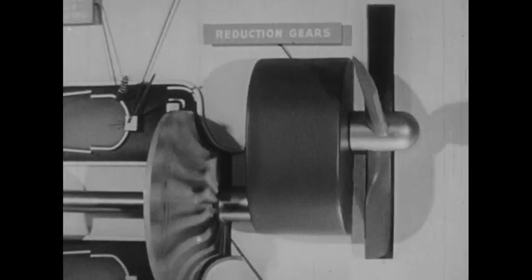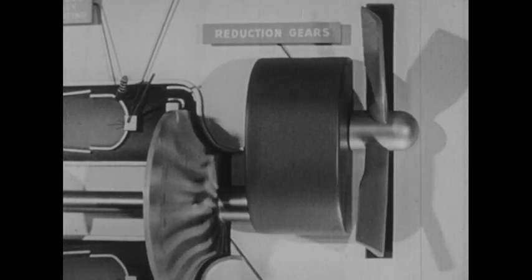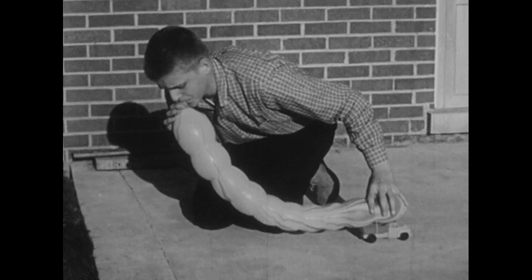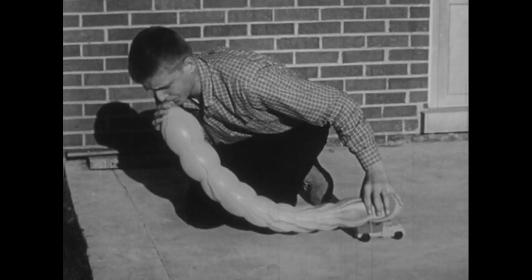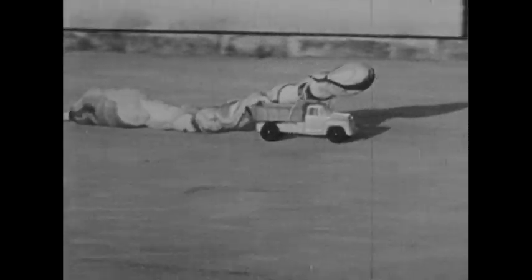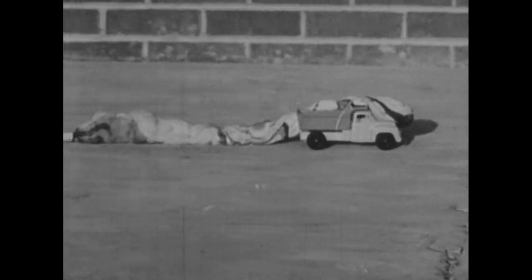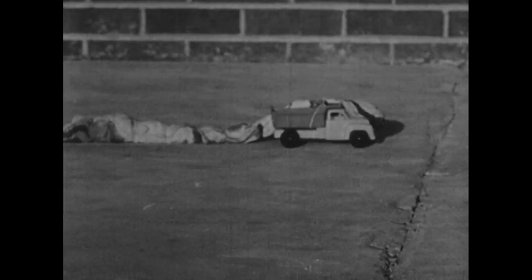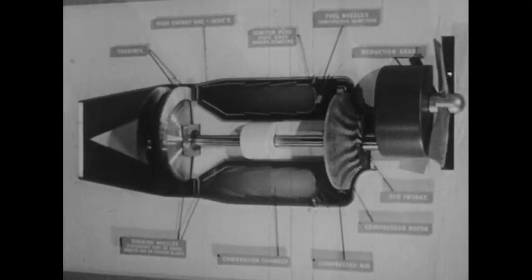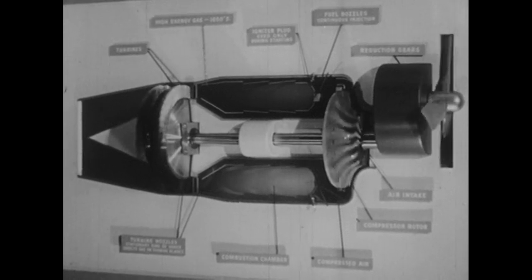The hot gases that turn the turbine, which makes the propeller turn, rush out the back of the engine. In a small way, this action helps move the airplane forward, as air, when it rushes out of a balloon, makes the balloon move in the opposite direction. We say the movement of the balloon is a reaction to the movement of the escaping air. While the turboprop engine is really a rotary engine, it is also something of a reaction engine because of the gases rushing out the back.